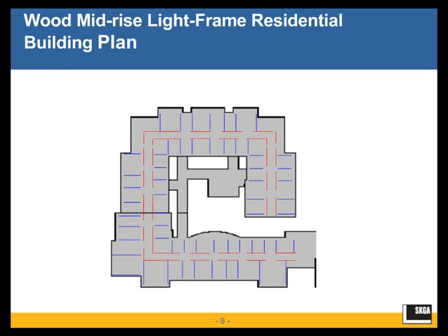Here's a typical plan for this building type. Note that virtually all the units only have one exterior wall. There is a perpetual negotiation at the exterior for reducing walls to maximize windows and the need for natural light versus lengthening walls for the vertical lateral force resisting system.